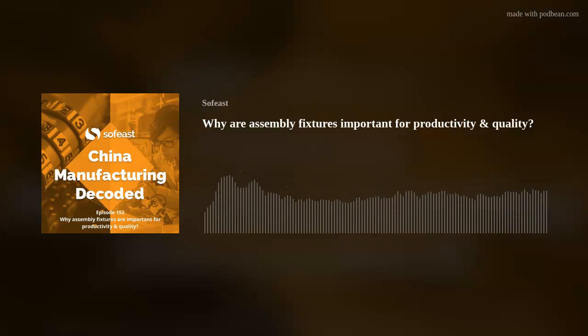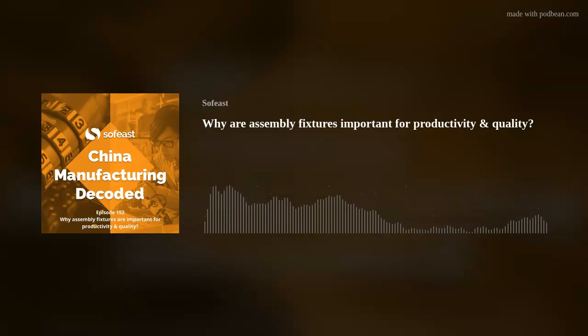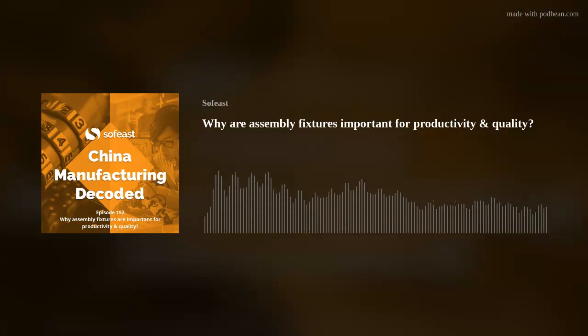Well, the obvious one, building on what you were saying there, from a dimensional point of view, the simplest check you can do on a production line, for example, is take the component and it's got a tolerance on the length, for example, and you've got a simple go, no-go gauge on the assembly place where you're actually doing that.